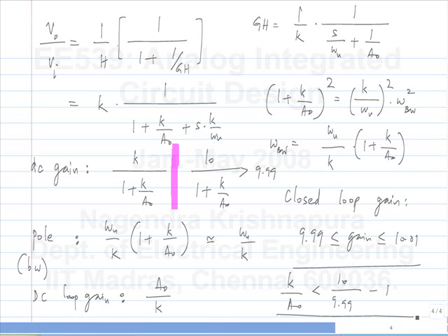Okay. So, what is the minimum DC gain of the integrator you need? The loop gain is 1000. What's the DC gain of the integrator? That is the closed loop gain times the loop gain. So, that is 10,000. So, you need a minimum loop gain of 1000. Okay. So, you can see the error is 0.01, right? 0.01 divided by 10 is 0.001.